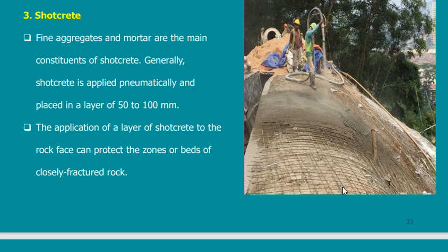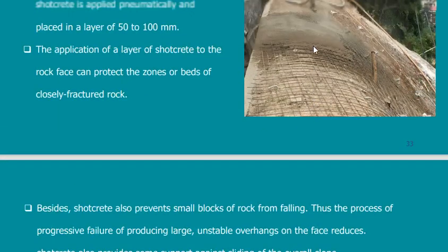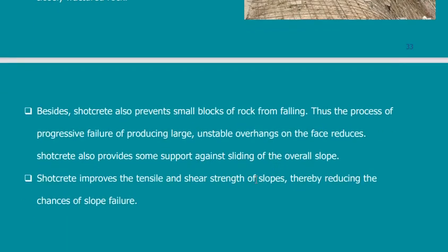So I end up having a concrete slab, but instead of having a slab with a specific shape, it is variable in shape. It takes the shape of the rock. So it covers the rock as if I'm having a concrete slab covering the rock everywhere I go. So it is another way for fixing this slope.